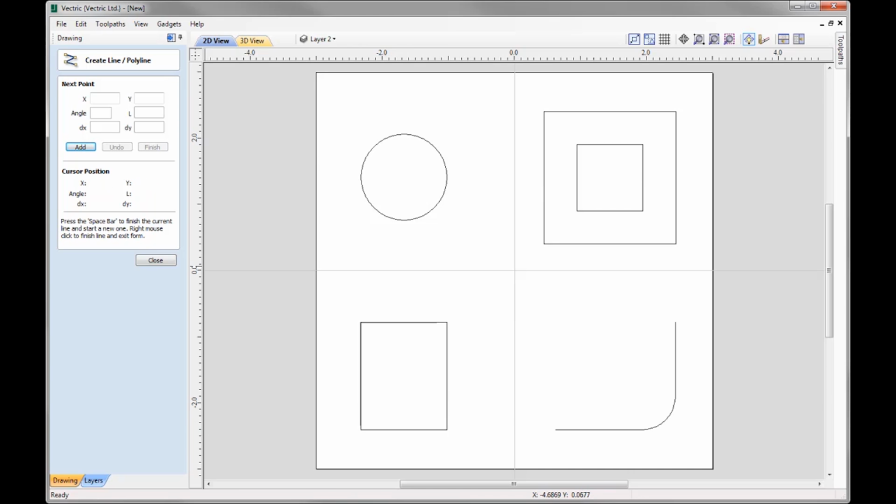So we've looked at the object bounds, we've looked at horizontal and vertical lines and angled lines. Now Smart Cursor can also pick up tangent lines. So let's wake up this circle here, and if I just move my mouse along, you can see that the software has found a tangent line, and I can click and then I can just follow along that line, click that in place. And the software can also pick up lines that are perpendicular to tangents from nodes or midpoints. And so you can see that we're displayed with that right angle there. And that's the software's way of telling us that it's found a line that is perpendicular to that tangent.